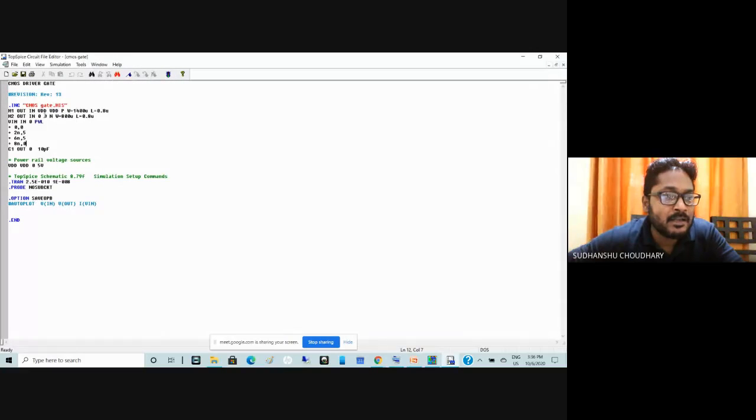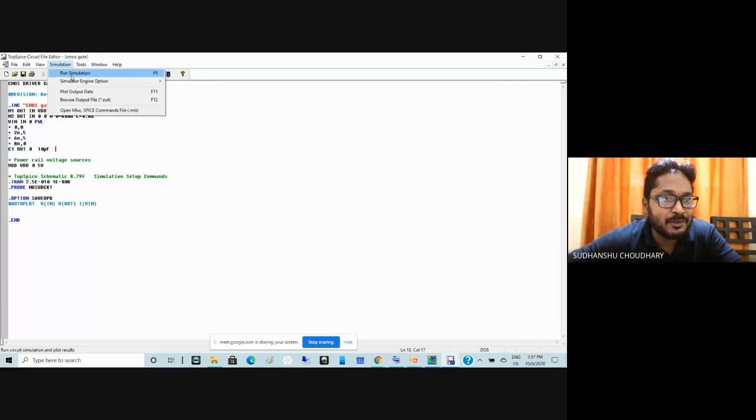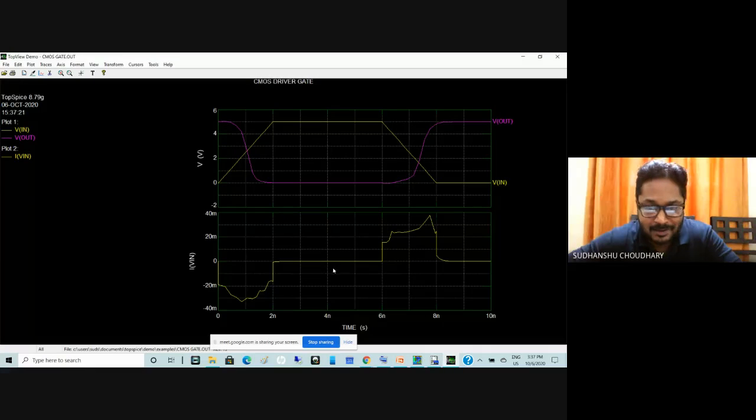Yeah, and then you can change these MOSFET parameters. For example, you can change the width of the MOSFET, the length of the MOSFET. As per our assignment, you can change the width and length of the MOSFET, and then you can also change maybe the VDD or maybe the output capacitance. So all these things can be changed, and also the transient response values, the input and output, all things you can change, and then maybe you can run a simulation. If I run a simulation, I get the input versus output characteristics. The input is here in yellow and output in purple. And then from this input and output, you can locate the 50%, 90% and 10% times, and then find out the propagation delays or rise time and fall times. All these things can be extracted.